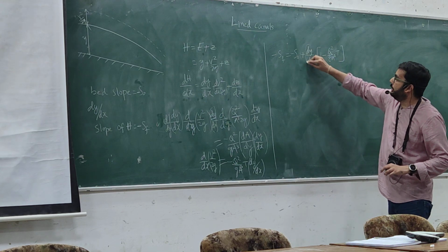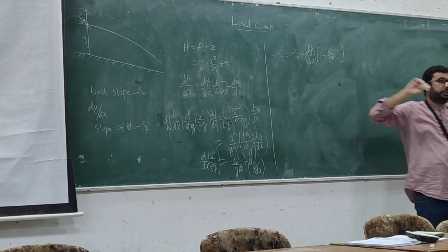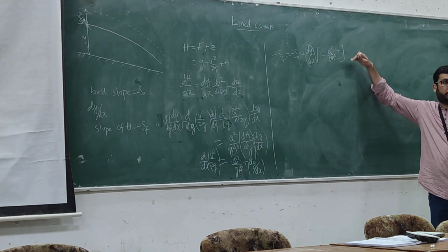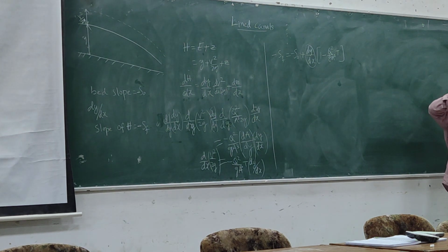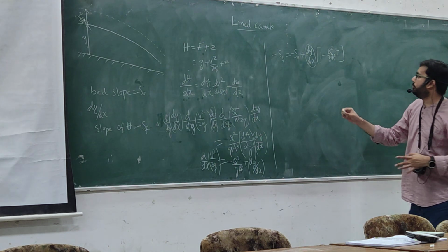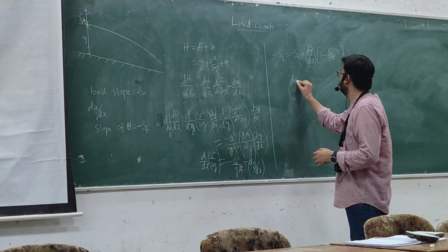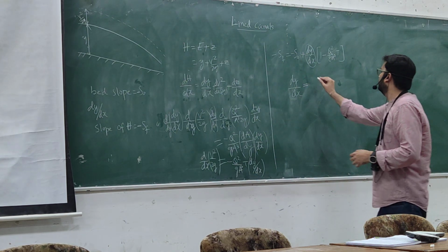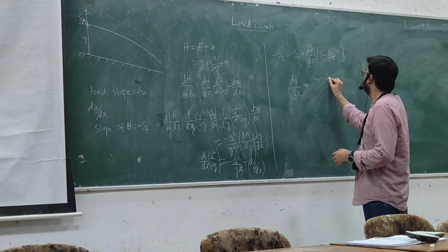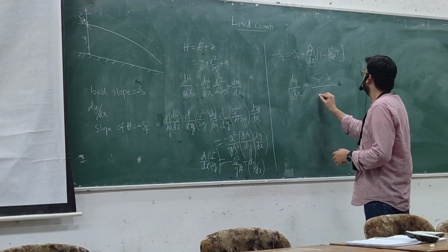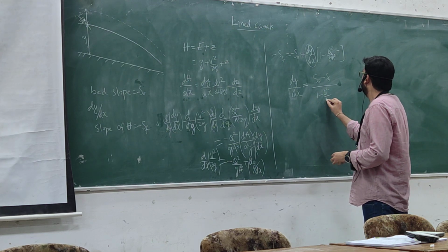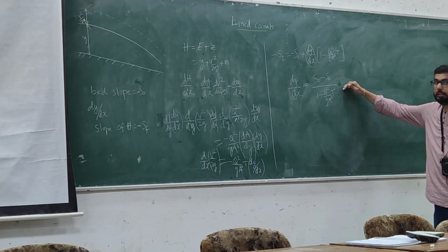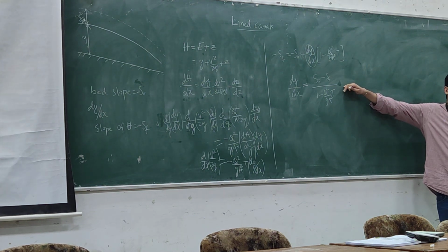Now we are interested in how the flow depth is varying with the distance x. So if we find this relationship, then we are going to use the control point and calculate backwards what the flow profile is going to be. So this is the relation that you would get for dy by dx.